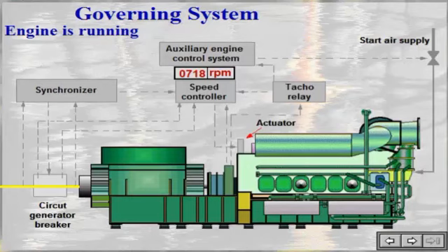When a change in the load in the main bus occurs, the generator will be forced to increase its output. Since the engine speed is constant, determined by the frequency on the main bus, the increased load from the generator results in an automatically increased power output from the engine by increasing the admission.